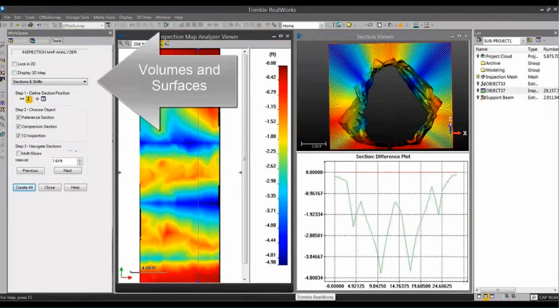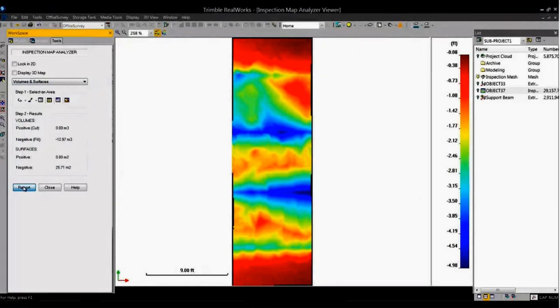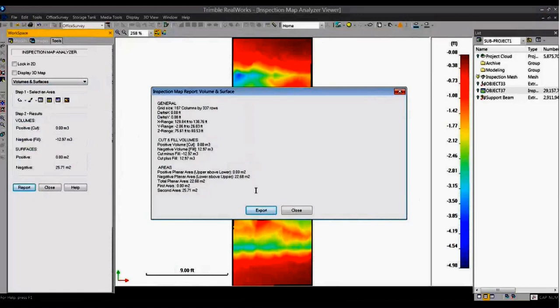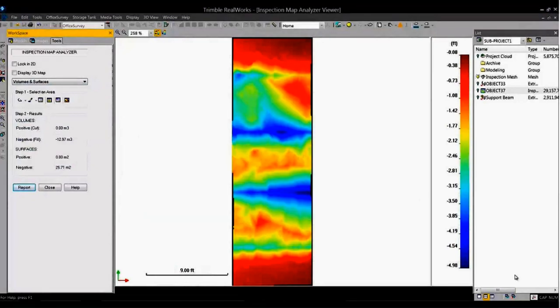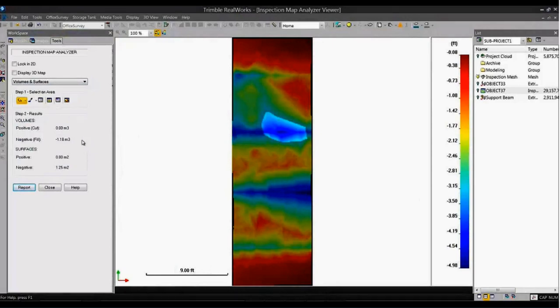Maybe blasting is going to be involved in some spots. I can pinpoint those. I might need to know how much material needs to be taken out of here. So I could, in fact, go in and maybe not just create that simple model, but create an extrusion to go along a section of the tunnel, and then compare that shape to the tunnel itself to know exactly how much material is going to need to be removed.